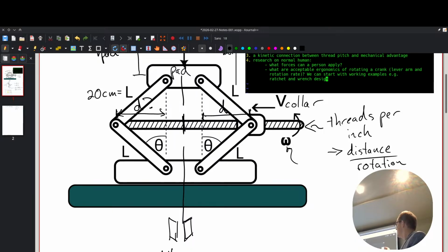Like we have 1, 2, 3, 4, 5, 6, so 6 different moving parts, but they have all these constraints that they have to move together. Even the left arms and the right arms. If I change the angle of one, we're assuming the other one is just going to follow it. So there's a lot of constraints put on the system by us, the engineers designing it. The more freedom you have, the more you have a car jack that's falling apart and you need multiple support structures to keep it in place. So it's nice to have single degree of freedom systems, at least for this.